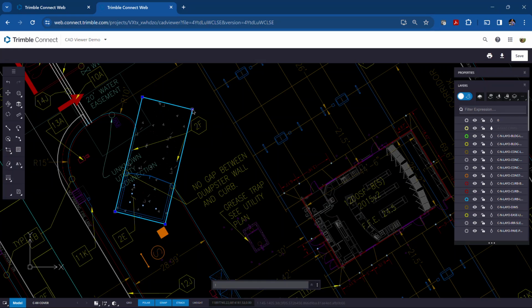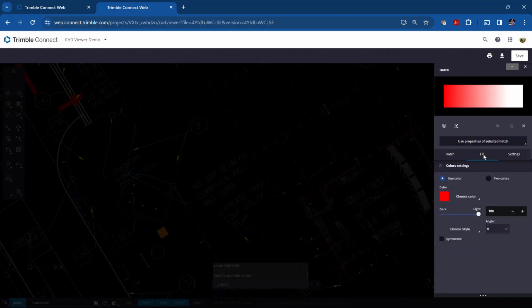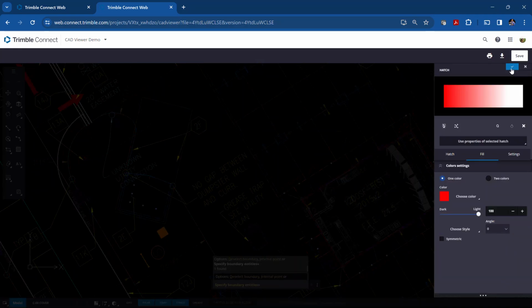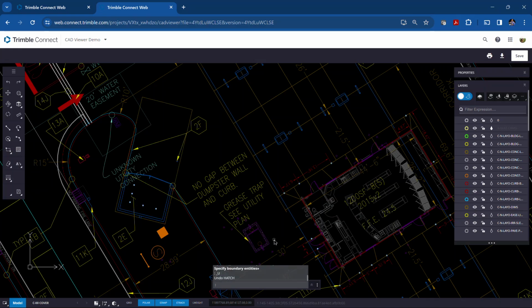The boundary is this object, and you'll see that if I stretch that, the hatch pattern moves with it. If I pick that object again and delete it, now let's do the hatch pattern. And if we were to do a fill pattern, again selecting that object and I pick that boundary line, right click and press enter, and then click the plus, you'll see that it fills it in as that shaded pattern for us. I'm going to press Control Z to undo. So that's the hatch pattern.